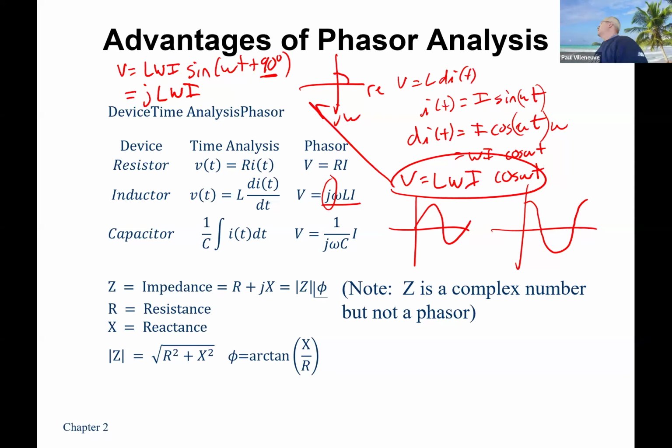Very, very important. Most of the time, if you were taught about impedance, somebody probably just waved their hands and said the j term was there. They might have derived where the omega term came from. But more often than not, people just say, well, there's a j term in here because we have to account for phase shift, and they never really show you. But it really is not that complicated. It's just that the sine wave has to be phase shifted by 90 degrees to get a cosine wave. That's the only reason. Okay.